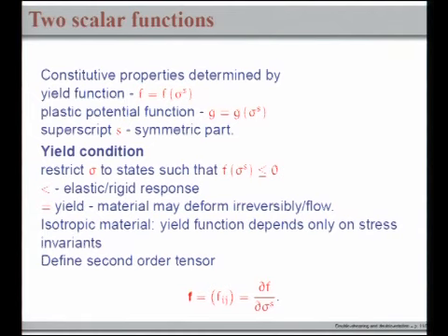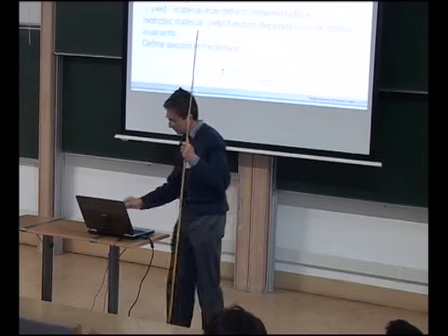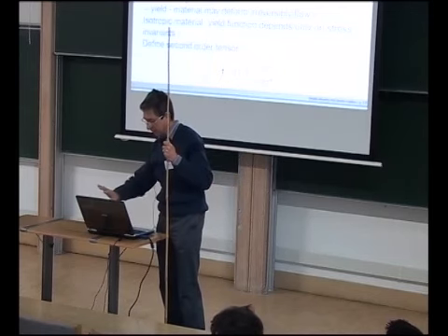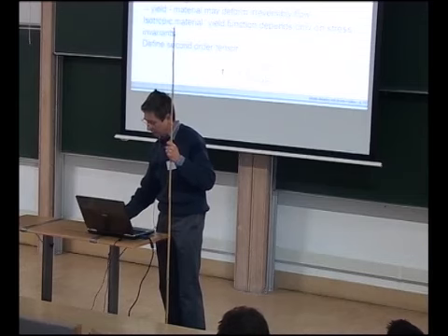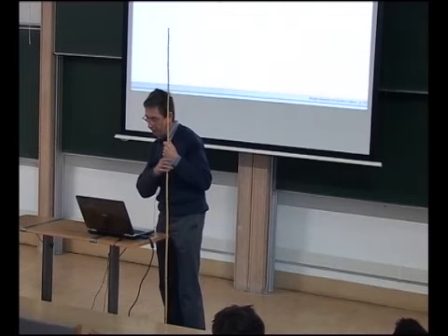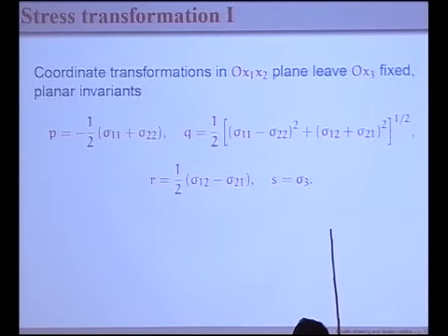And one point that I would like to make is that when we consider the system of partial differential equations given by the stress equilibrium equations and the yield condition, then all the information is contained in this second order tensor when we differentiate the yield function with respect to sigma. All the information is contained within that. The partial differential equations merely, if you like, conserve the information given by f.